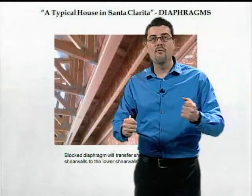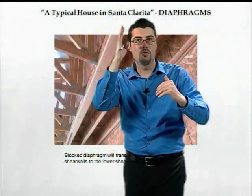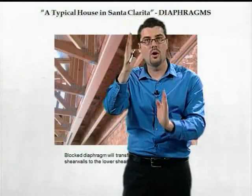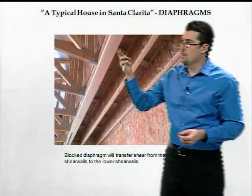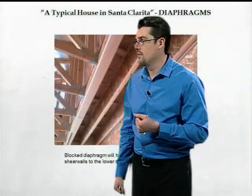Makes sense. If you were in the field and you saw, or you're designing a plan, and you see a shear wall that transfers from one shear wall through the floor to another shear wall, you're expecting that piece of floor to be much stronger. And so in this case, you'd block the diaphragm. You'd add that blocking to give it that extra strength.